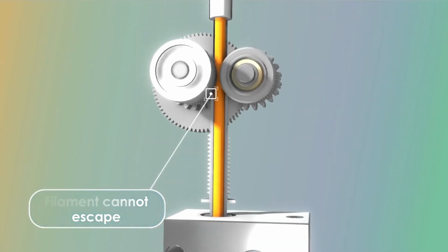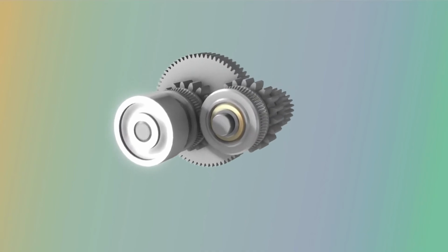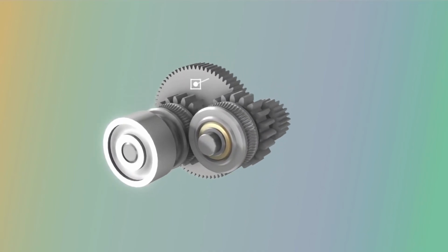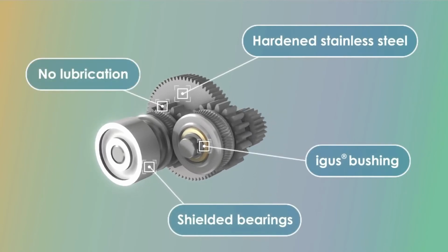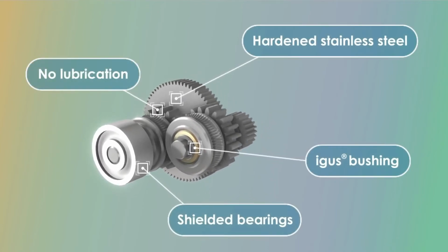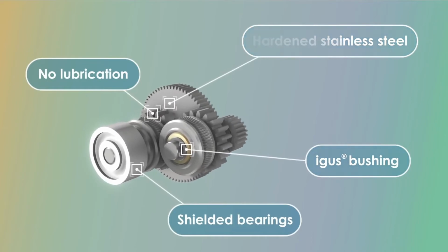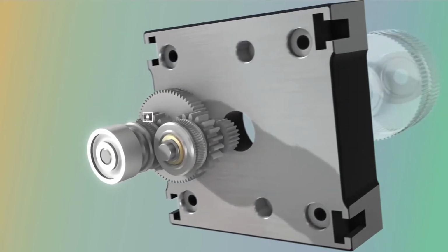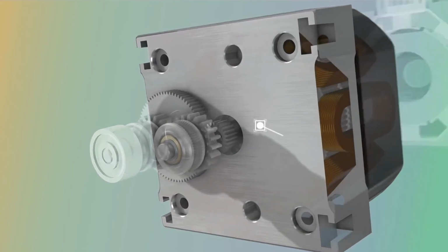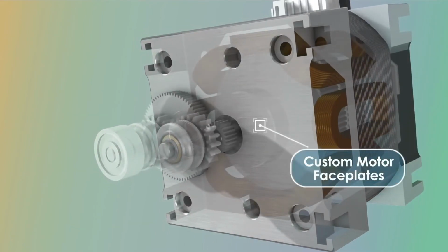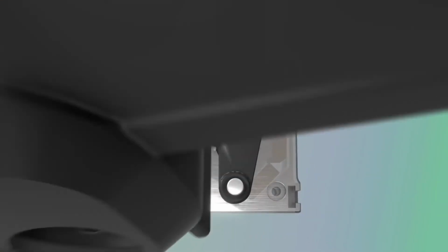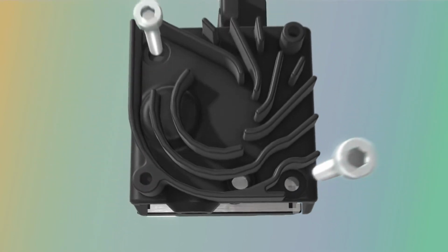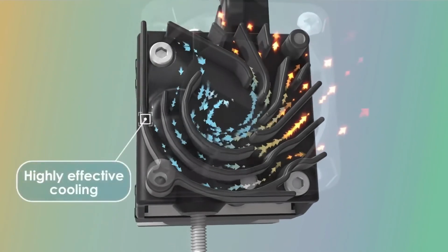As soon as the job is selected and activated in the print window, the machine springs into action. A combination of onboard preset actions and tasks specified in the top startup G-code from the job file trigger the mechanical system to move elements around in the operational envelope. It sets out to accomplish two critical tasks. One, the homing of the XYZ axes by moving the tool head and the build platform to hit the corresponding XYZ stops.